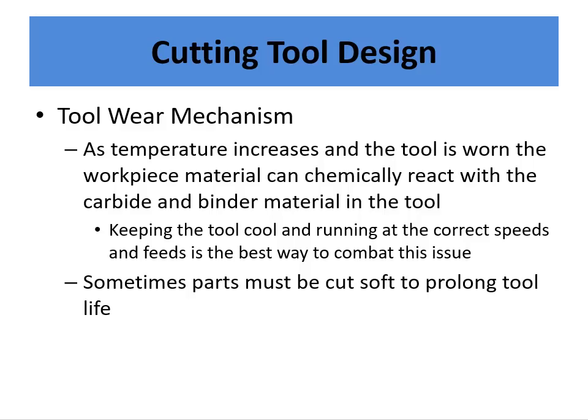So the chips kind of provide a secondary purpose of carrying away that heat. And between the coolant and the chip, hopefully the tool temperature can be kept down. And that's the best way to keep the tool life the longest generally. And sometimes you want to cut your parts softer versus harder.